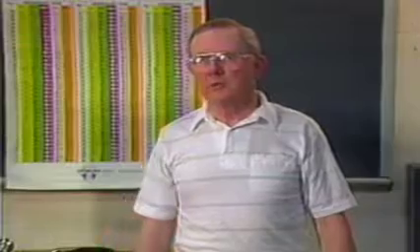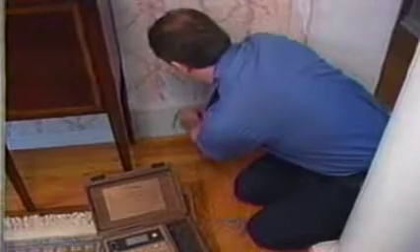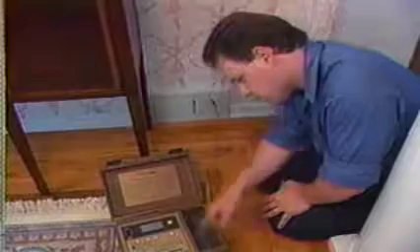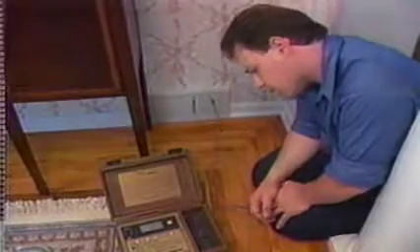Okay, let's go to a video. A dry bulb wet bulb reading is taken to determine the humidity. A cotton sock with pure water is placed on one of the temperature leads. This lead may now be used as a wet bulb indicator. A wet bulb and dry bulb reading to determine the relative humidity and the latent heat load on the coil may be obtained by placing a dry bulb temperature lead next to a wet bulb lead in the return air stream. The velocity of the air will be enough to accomplish the evaporation needed for the wet bulb reading.